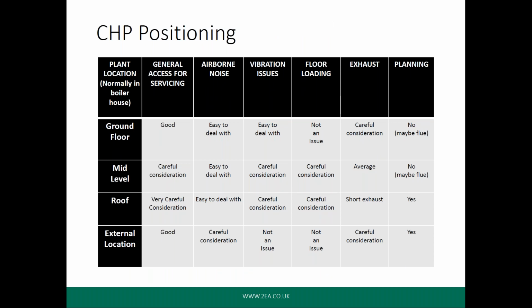Finally, a brief look at some of the pros and cons for the choice of combined heat and power unit location. Again, this slide is pretty self-explanatory, but I would like to take a moment to focus on the servicing aspects of combined heat and power units. Providing good access for servicing is often overlooked, and this is linked to a whole other topic that has to be considered. A combined heat and power unit needs regular maintenance. If it doesn't or can't run, it's just an expensive white elephant.